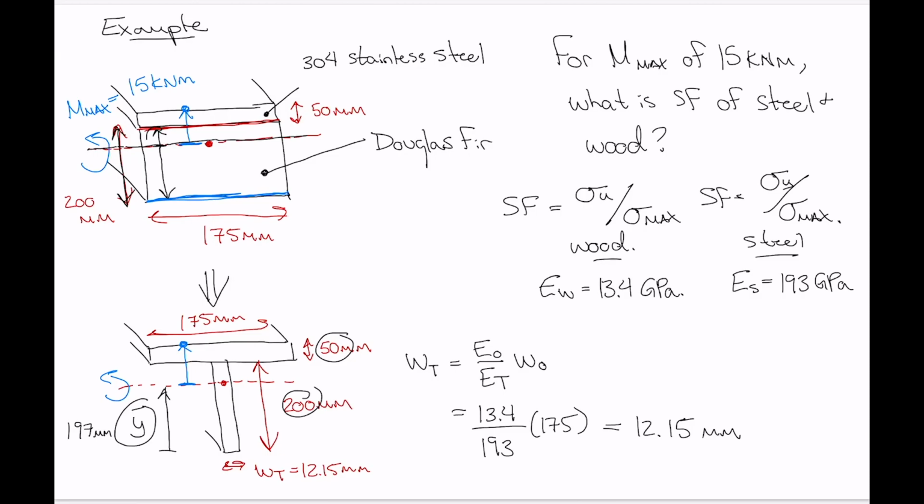So the value of Y going from the neutral axis of bending to the farthest point away in the wood that would experience compression can only be a maximum of about 3 millimeters, which means that the compressive stress is going to be really tiny. So even though the compressive strength of wood is less, we can safely assume that the wood is going to fail in tension, and just look at the point of maximum tensile stress.